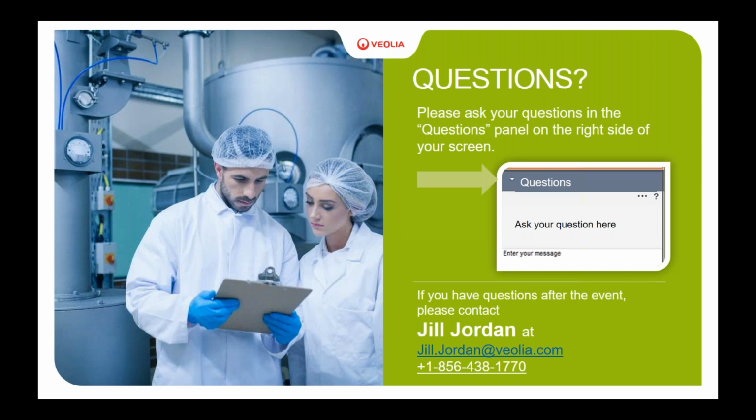A lot of times, like Timur talked about, these composite samplers can be set up to take a sample once every hour for 24 hours, or once every so many gallons over a 24-hour period, as separate samples. Analyzing each one of those samples over the time period gives you a good idea of how the flow and loads vary over the day. And analyzing those is what determines how much upstream pretreatment you're going to need and what that might need to be.